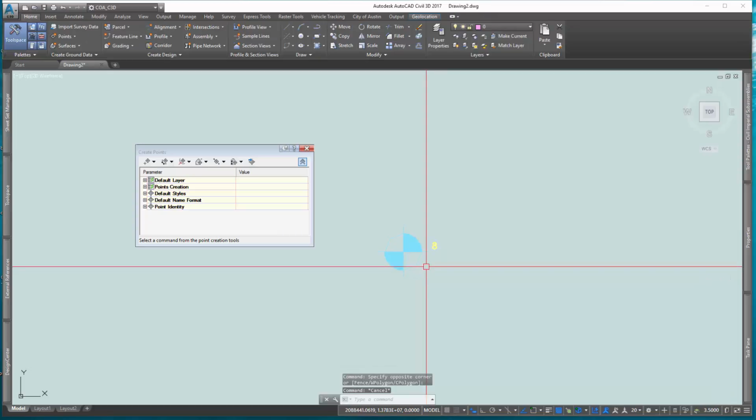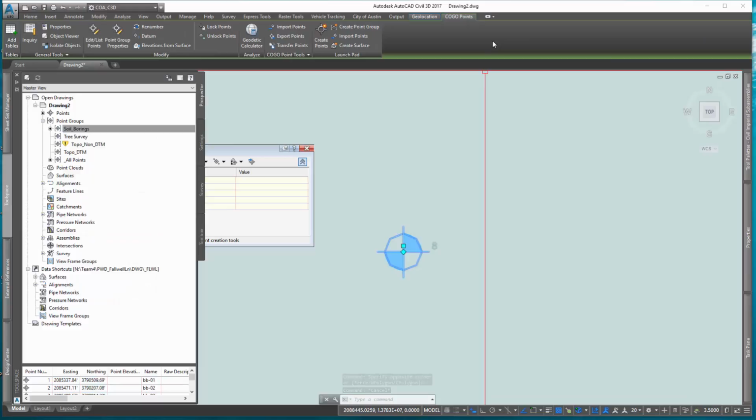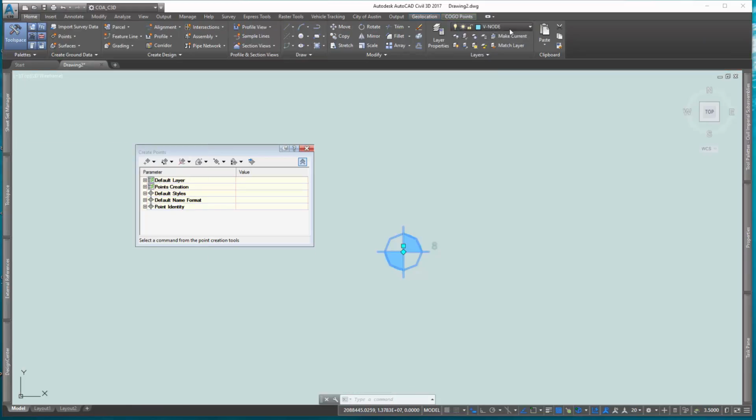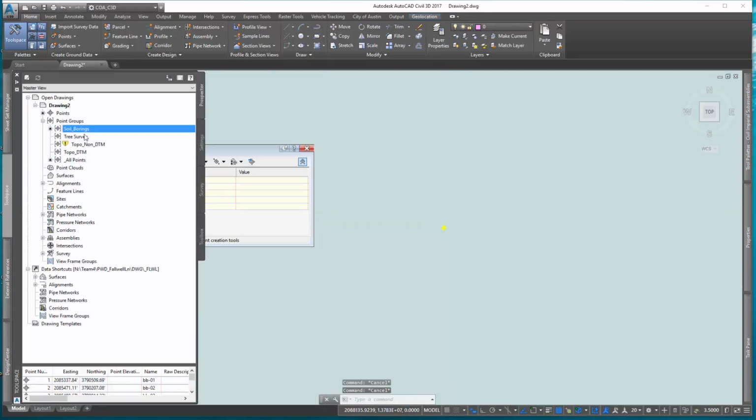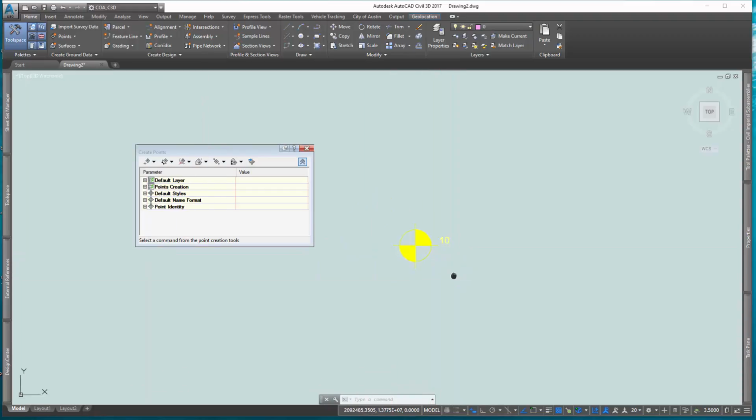There you go. Now the other thing we can do right in here, select all the points, and you can put them in the right level. So we're going to select the points and change the level for the points to the right level. Okay, now this was the first way to import points. We're going to focus on the second way to import points by using one of the tools available in Civil3D.